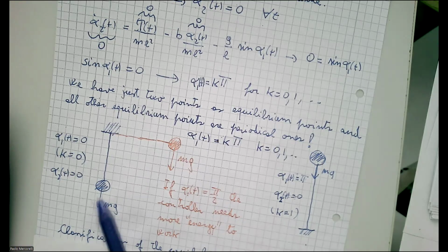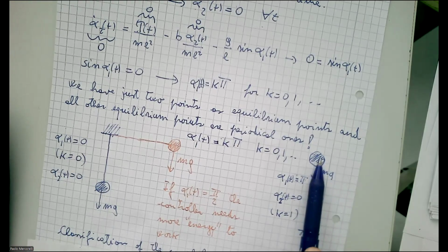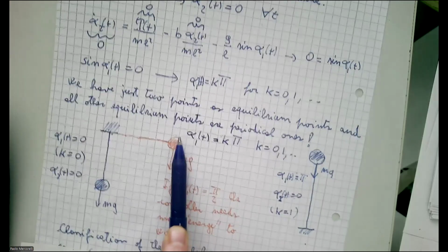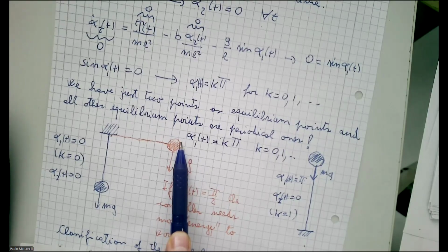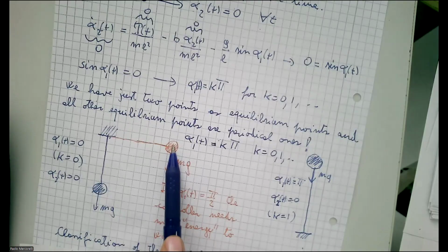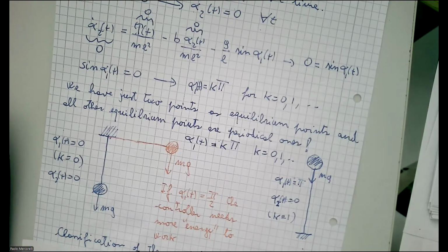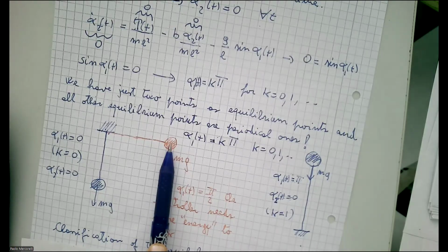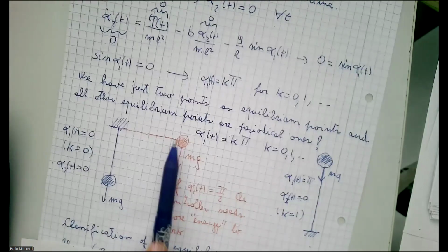It's more difficult than to control, in any case, the system at this point, but also more difficult than to control the system at this point here, because this is not an equilibrium point at all. It's really the farthest point with respect to this and to this. To control in some other points could be, in general, easier than to control the system here. Why that? Because here we have the maximum torque generated by the gravitational force. This means here, really, we have to energetically spend energy.